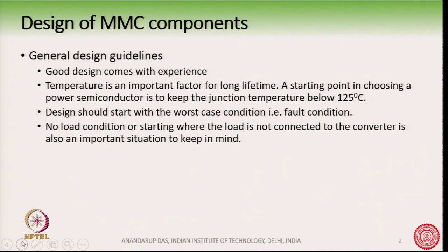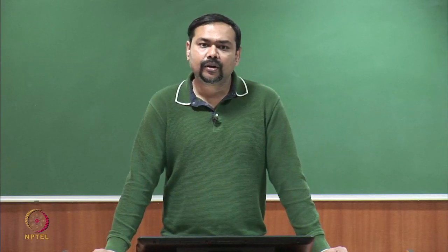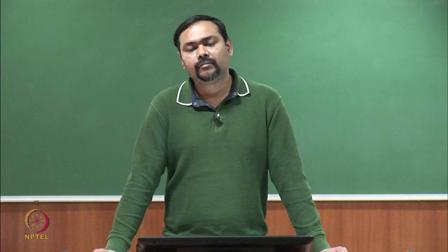Now, when you design a system, it is very important that you take care of the temperature. Temperatures are very important for long lifetime operation of the converter equipment. We generally follow the Arrhenius rule when in the industry. It is not very mathematical, but it is a general thumb rule that every 10 degree centigrade rise in temperature will reduce the lifetime of a component or a converter by half.